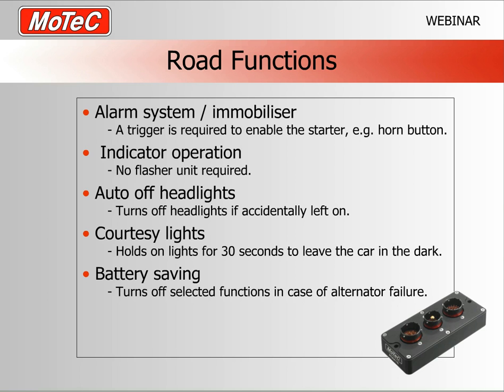The other thing the PDM is very good at is in the situation where you have, for example, an alternator failure, the PDM can use a keep alive function whereby the important things such as the engine, the cooling system and so forth are powered, but the PDM can remove power from such things as the subwoofers or the air conditioning system, and therefore the car effectively has a limp home capability that would have otherwise not been there.